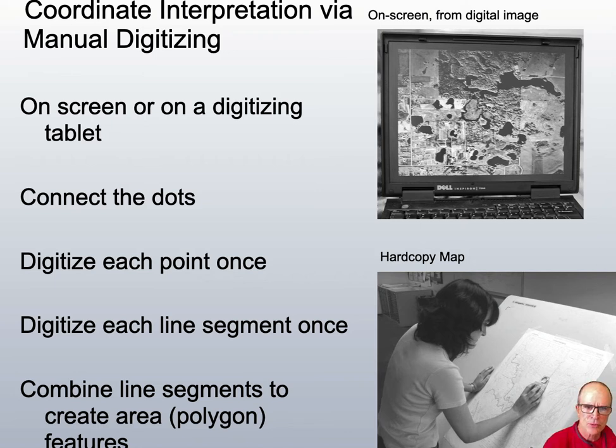So on images, we're laboriously displaying and then collecting boundaries, like the boundary of the lake. We hold a puck over a location and press a button to say, here's the edge. Now, there's a lot of automated image processing, and image processing gets better and better, so we can pull a lot of these edges out, like water-land boundaries, pretty effectively using automated digitizing.